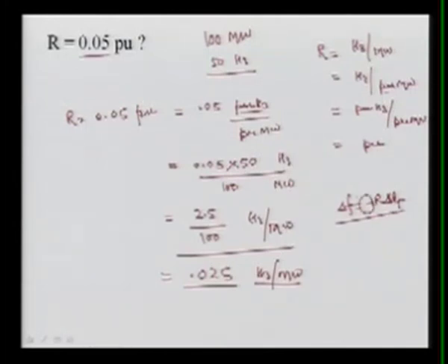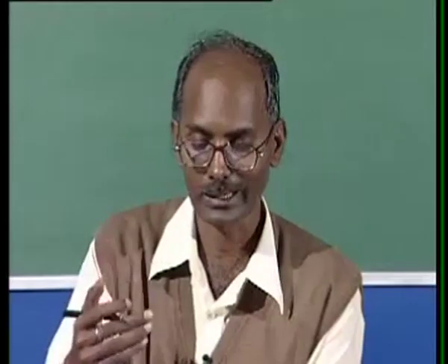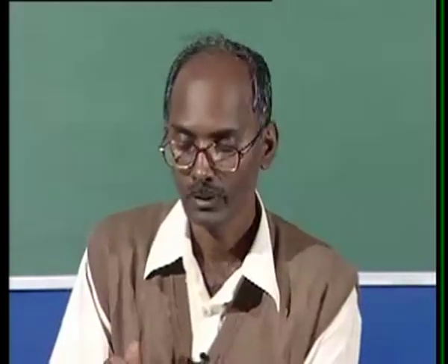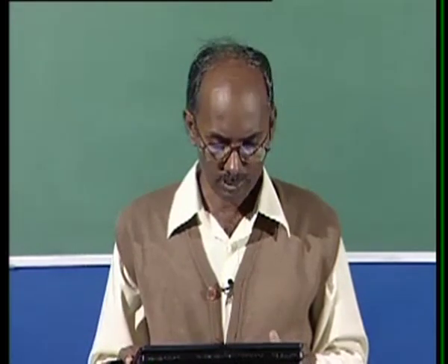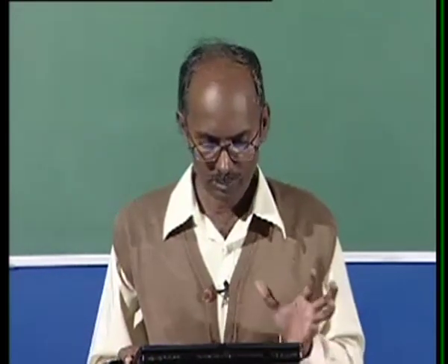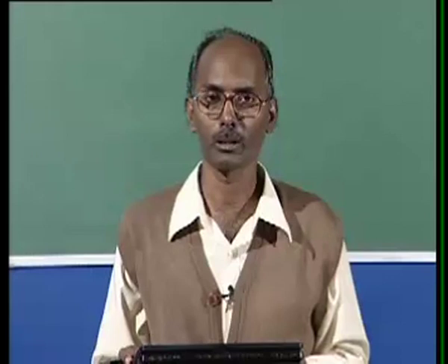If you increase the turbine power, the system frequency will decrease. But if the frequency falls, this turbine will automatically try to increase its output, because of the R sign. So this is basically the concept of R, that is the regulation. So we saw the combined effect of governor and turbine.